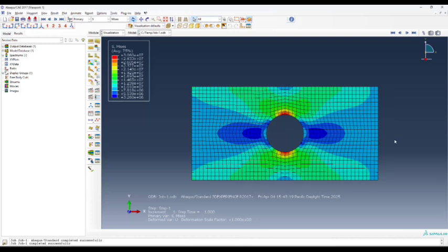Ethan, inch, pound, second, that would be, like I said, everything is kind of defined by you in your own definition. So if you want to do inch, pound, seconds, you assign whatever lengths you want. Your forces, you assign them based on your own calculations, material properties based on your own calculations, etc. It's done independently on your end. Everything is dimensionless in Abaqus. It's really up to you to do the math on your own end. That makes sense? It's not like SolidWorks, where it's going to have you assign a dimension system like inch, pound, second, SI, meters squared.